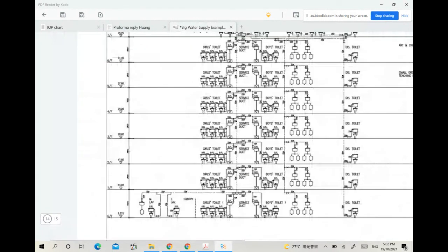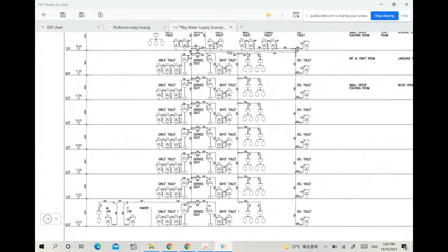Now, in the design, if I'm correct, you are not required to conduct the flushing water design. Am I correct? I don't remember. Now, don't worry. The design for the fresh water and flushing water, I treat the same, except for the discharge pressure. For the flushing water pipe, you are not required to consider the discharge pressure. Do you know why?